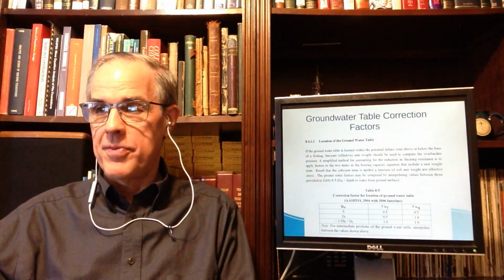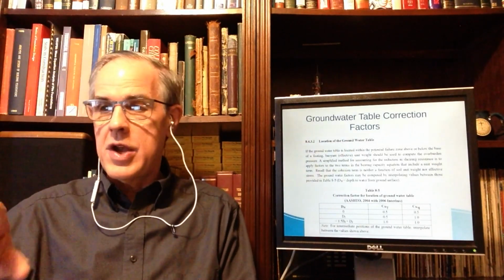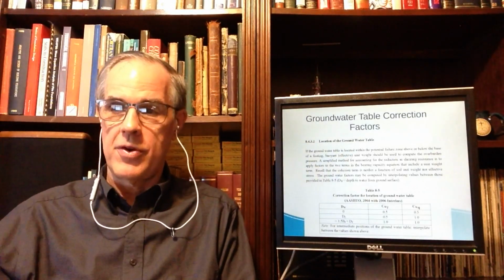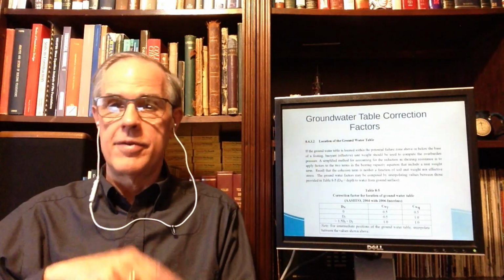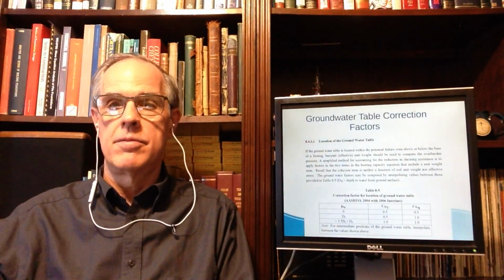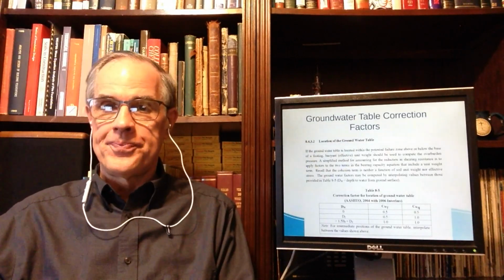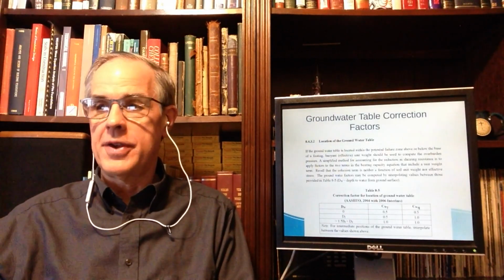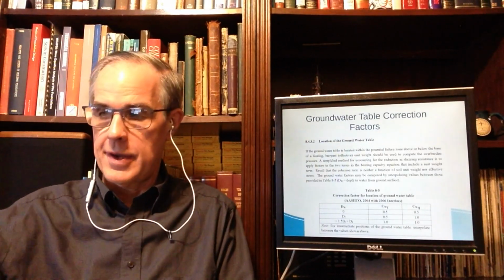And you must use this, and you must essentially linearly interpolate between those points. In other words, from 0 to Df, and then from Df to 1.5 Bf plus Df. Those three points. If it's below it, it doesn't matter. The water table is, as we say, very deep. So those are your groundwater tables. It's probably the simplest one I've seen to implement and the easiest one to follow, which is probably the reason why AASHTO adopted it.